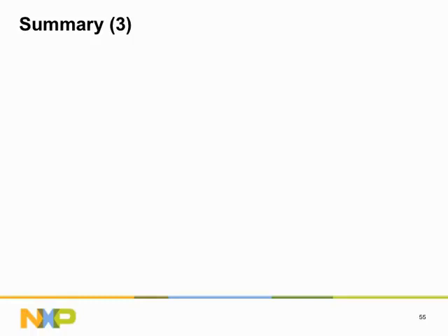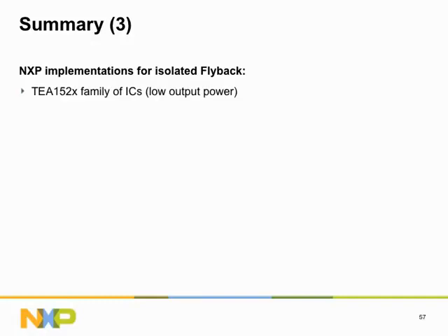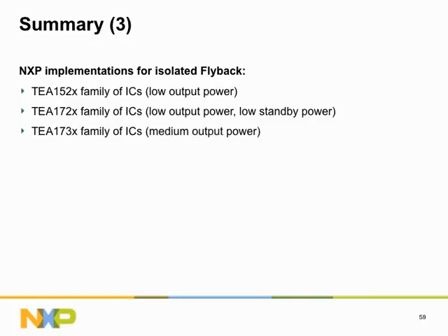For isolated SMPS solutions, we have seen two main topologies. Let's have a look at the IC implementations that NXP has for flyback SMPS solutions. TEA152X for low output power, TEA172X for low output power in combination with low standby power, TEA173X for medium output power.